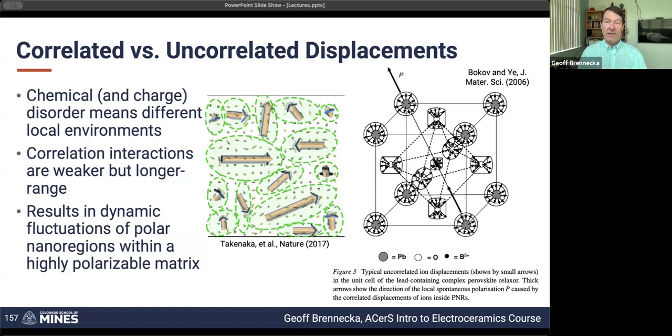Sometimes you can end up with a system that is self-correcting. So it essentially jumps on whichever site is going to minimize the number of extra dopants or extra defects that are present, and ends up self-compensating for other impurities that you might have around. So that's one of the nice contributions of those middle lanthanides, both to PZTs and to barium titanate, is that if they can go on either site, then a lot of times you can end up self-compensating for other unknown, unintended impurities. All right, so back to relaxers.